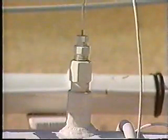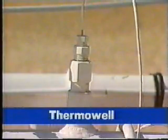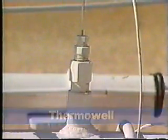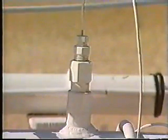Several components located on a meter run are not considered part of the primary element. They are, however, important in the accurate measurement of NGLs. The meter stations at your location may have all or some of the following associated components. Thermal well. The thermal well provides a location where the temperature of the NGLs can be measured. Thermal wells are usually located downstream of the metering device, as they can create unwanted turbulence.